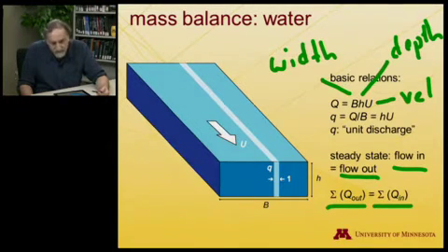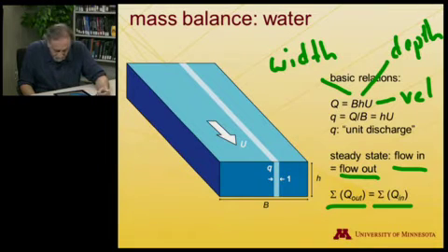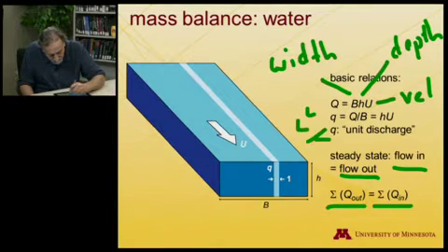Now, another quantity that will sometimes be helpful is the quantity that you get by taking that discharge, which is capital Q here, and dividing it by the width, B. The reason is that in many cases we're interested in what's going on in a single slice of the channel, and for that it's convenient to have an expression for the velocity normalized by the width. That's especially useful if things don't vary too much across the width of the river. That quantity is traditionally written as little q, and yes, I know this is a symbol that we've used before, but this is the traditional symbol for this discharge. It's called the unit discharge, and it's just the product of the velocity and the depth. So it's hu, and it has dimensions of length squared per unit time.